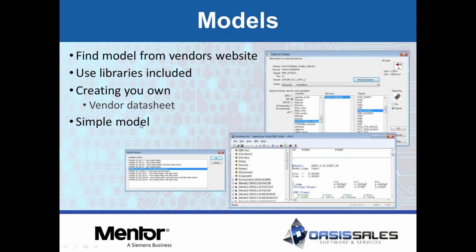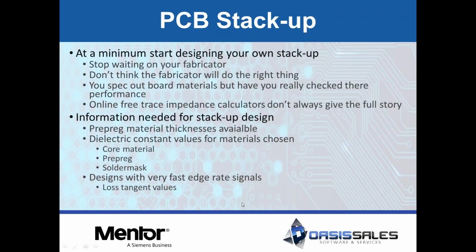And then simple modeling. Again, if you just want to create a simple model of a pin, that is possible in most signal integrity tools, so that you can at least get some idea. Just give me a 3 nanosecond edge rate with some basic output impedance, so that I can check my structure on my board to make sure my stack-up's going to be fine and my impedance of my traces is going to be fine. And a lot of this stuff is very simple, and I'm going to show that here through demonstration.